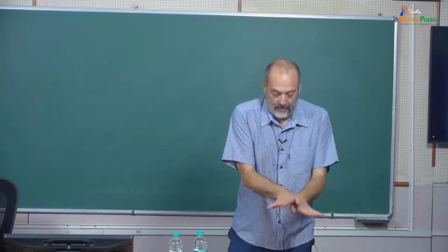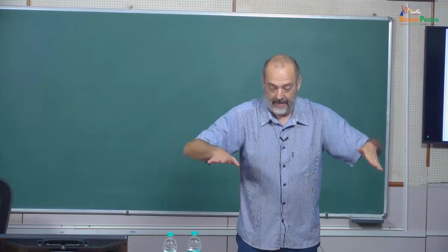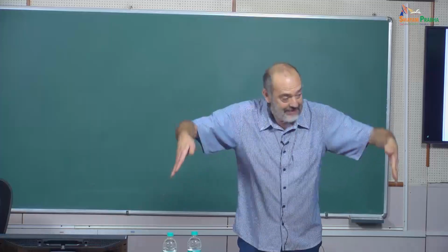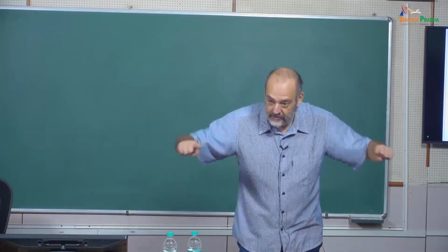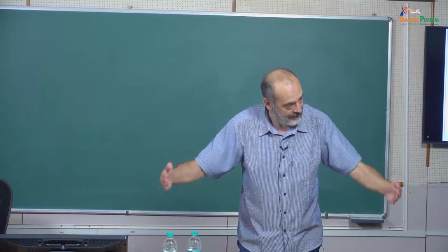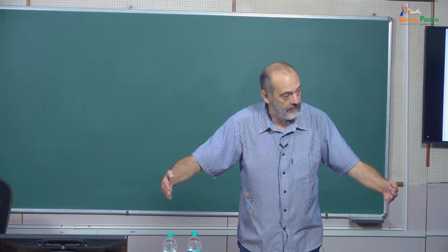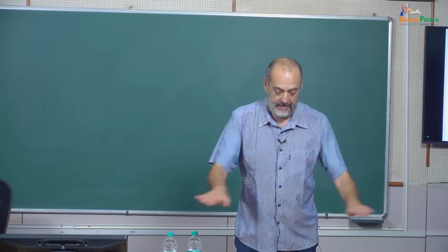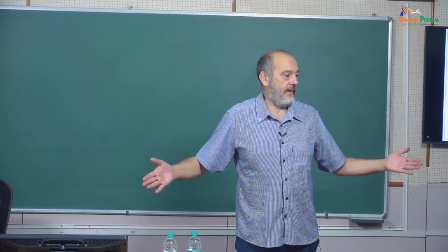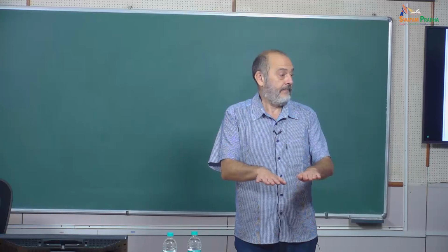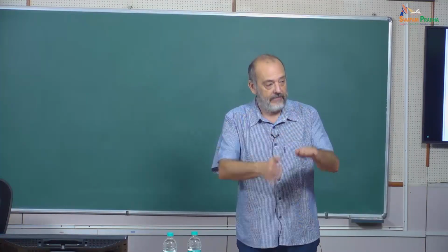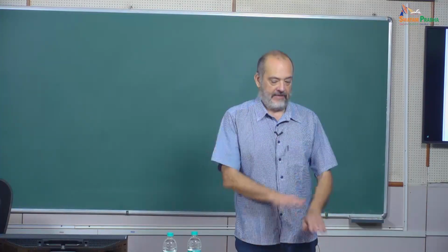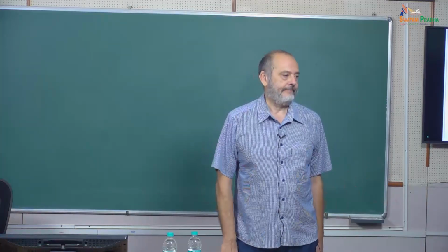Imagine to have a liquid surface like that, and then where is the most important point? It's not here, but at the wall. At the wall is going to be important because we are going to have a change of the curvature at the wall with the effect of the contact angle and so on. But here in the middle, there is no effect of the sigma. Only when you are perturbing it. If you are perturbing the surface, you are giving locally a difference of curvature, then the surface tension is playing a role. But if it's ideally flat, there is no.